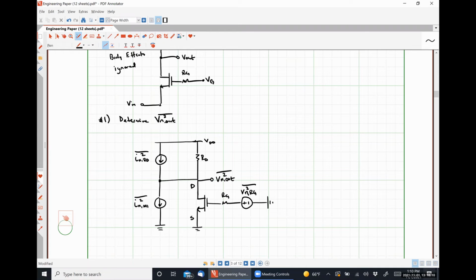All right. Now, the noise voltage that is generated by our resistor RG, I'm drawing it explicitly here because it might be less intuitively obvious how that will wind up as a noise between the drain terminal and ground, right? So with this configuration, we have to think about how this noise is going to contribute to that output noise, right? Anybody have any thoughts?